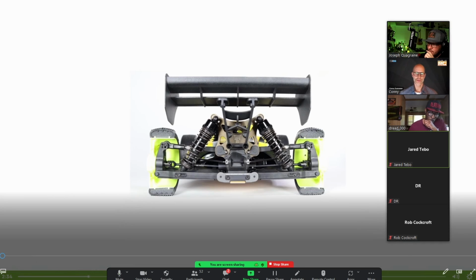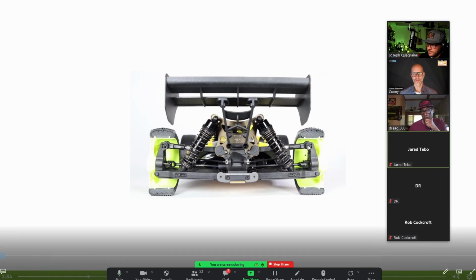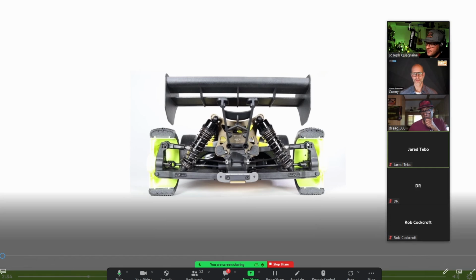And then finally, you are also able to adjust the entire height of the link. So you could lower the link on the inside and the outside and keep the same angle. That has a minimal change on the roll center. So I don't think of that as in the track or on the track. What that affects is initial versus overall grip, I can say. So the higher the link is, the less effective this link is at pulling or pushing on the chassis. So that means that it doesn't resist roll as much. It's more forgiving. A higher link is more forgiving for the same roll center height.